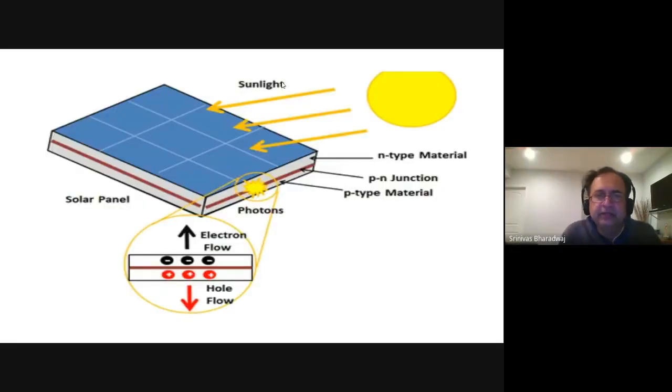The thick P is the substrate, then you have the junction between the P and the N, and then a very thin N on top. Typically it is a few microns at best, and the less they put there, the better for them. The whole thing is very thin, because the costliest part is making the crystalline silicon. When you have to make such a big version of it, the less silicon you use, the better.